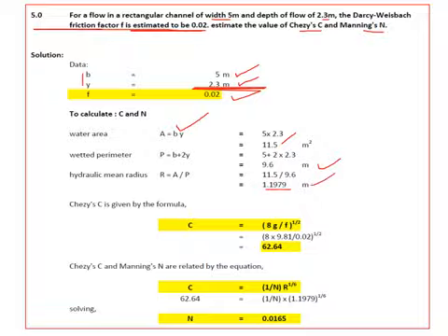Now you know the formula for Chezy's constant, which is root of 8g by f. So g is acceleration due to gravity, which is 9.81, and friction factor is given as 0.02. So therefore Chezy's constant is 62. If you know Chezy's constant, I already found out r. So you know C is equal to 1 by n, r to the power of 1 by 6.